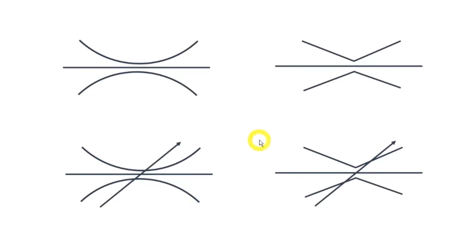When you see this angled symbol instead of a curve, it means that the valve is not dependent on viscosity, but it is still DP dependent. This valve here does not have an arrow, which means it is not adjustable. This valve is the same, but this one is adjustable.